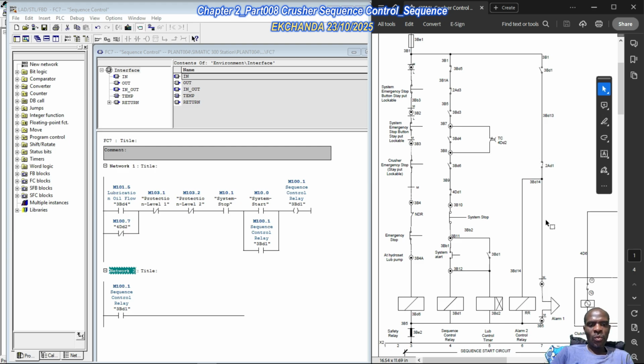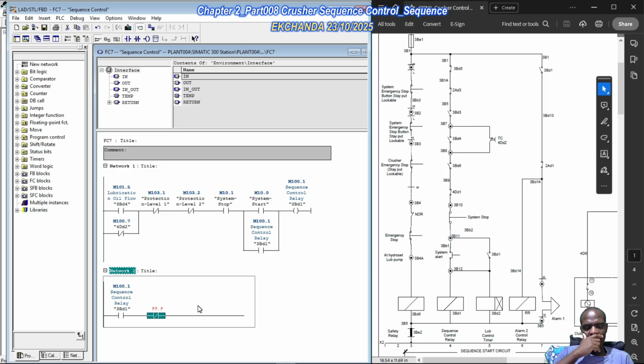So the pre-start warning siren is on between the time that the sequence control relay is energized and off at the point where the power contactor for the main drive is energized. Okay, so normally closed. Again, when you talk about 281, what is 281? 281 is a feedback contact. Okay, in as much as we're going to say 281, the right term would be 281 feedback.